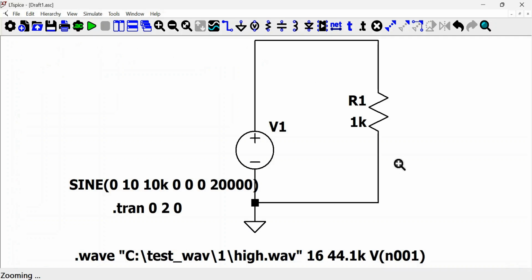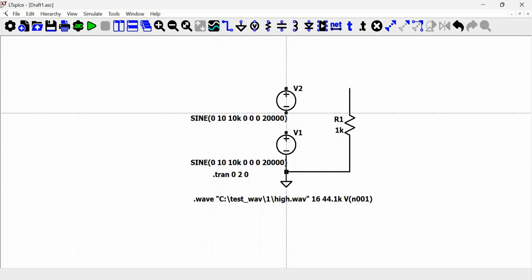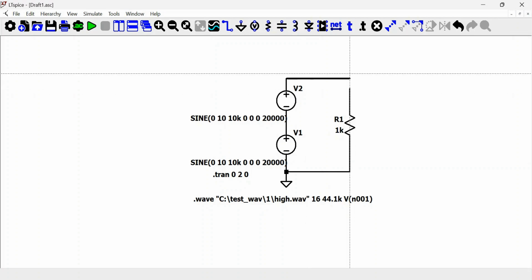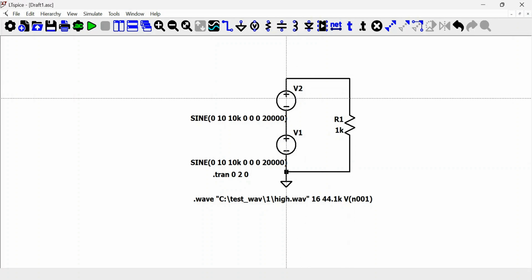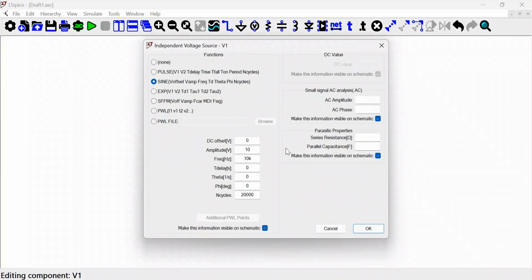So we go back to the simulation, and now we do something a little bit different. We add the two sines that we have created. So we Ctrl C, we copy the voltage source, we connect all the pins and the resistor too, and we change the first source.